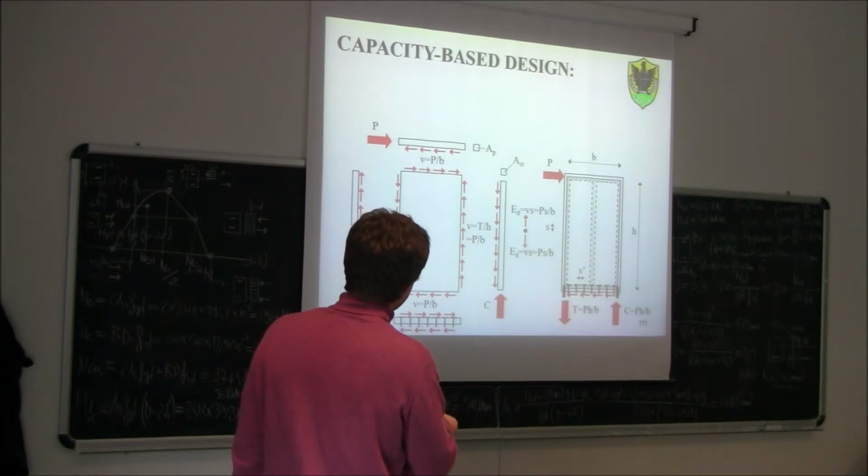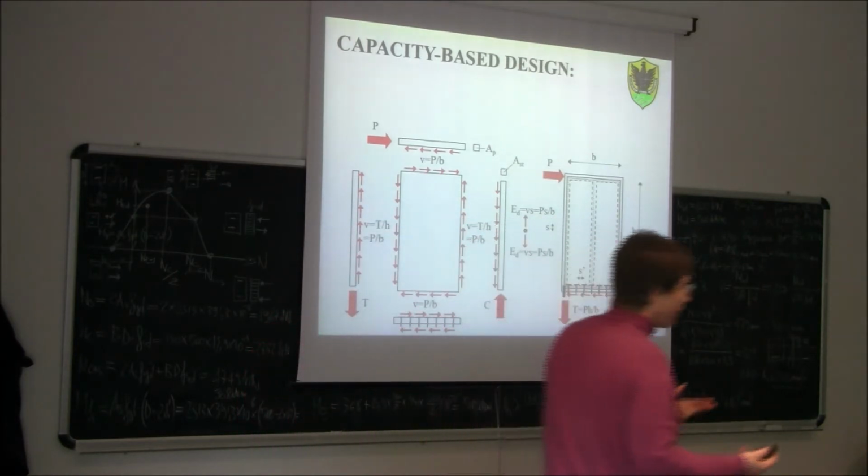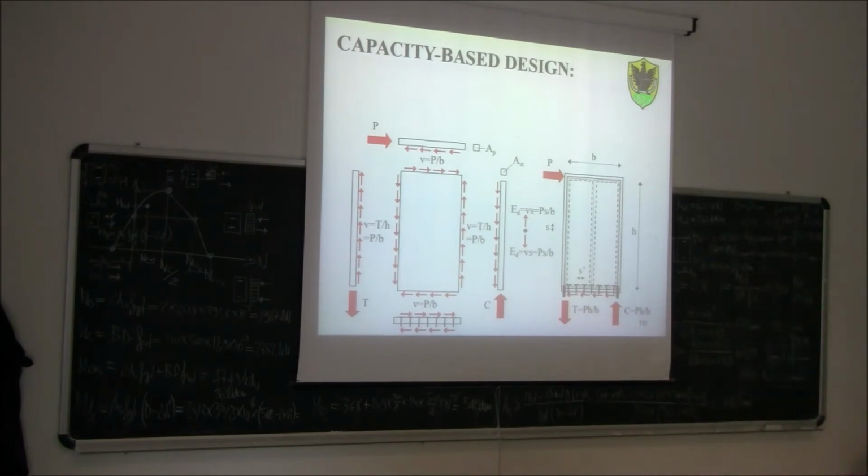The shear per unit length is the same on those two sides, because you remember that the shear forces are always the same, in the sense that the Cauchy tensor is symmetric with respect to the diagonal, so those two forces are the same.